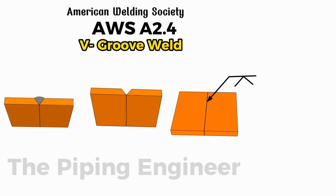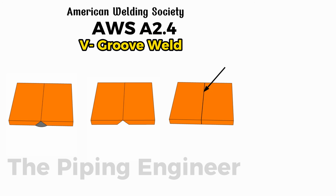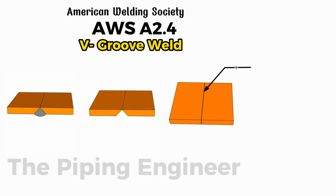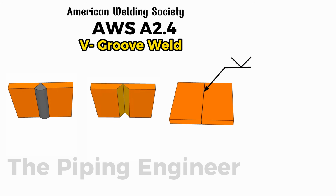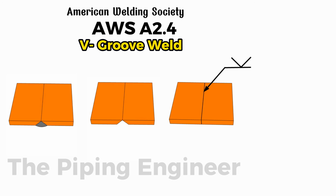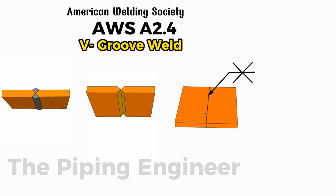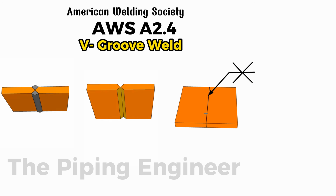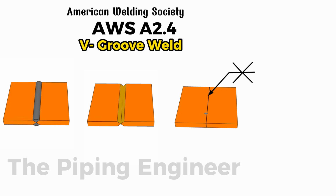Below the reference line, placing the V-groove weld symbol below the reference line instructs the welder to execute the V-shaped preparation and welding on the arrow side of the joint. Above the reference line, when a V-groove weld symbol is placed above the reference line, it directs the welder to perform the V-shaped edge preparation and welding on the other side, opposite to the arrow side, of the joint. On both sides of the reference line, when V-groove weld symbols appear on both sides of the reference line, it means a double V preparation and weld must be performed on both sides of the joint for maximum structural strength.